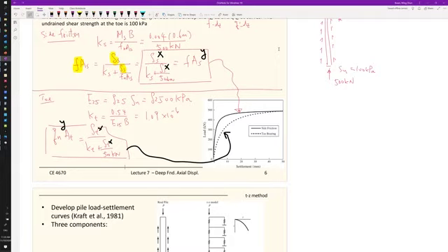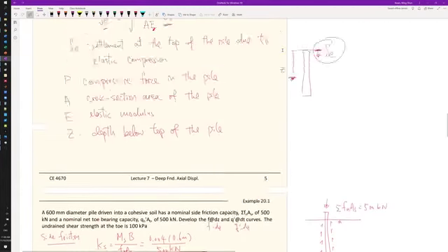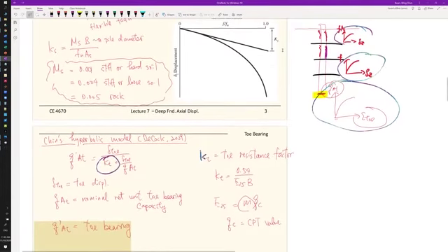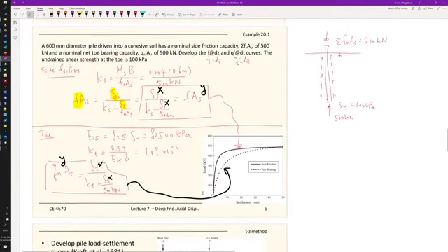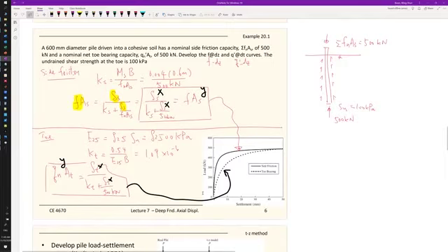The total settlement depends on the loading. Again, you have three components. So I want to break it down and make use of one hyperbolic model, the Chin's hyperbolic model, the Cook 2009 method, to walk you through the math behind it, and also hopefully help you visualize that it is indeed a curve. It is not just a single number when you calculate the settlements, and the curve describes the response between the loading and the